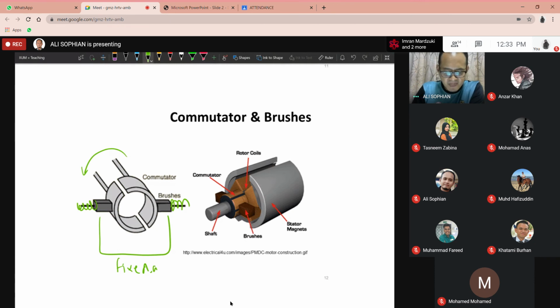The idea is, as the motor or the generator is aging, the brushes get worn out because of the friction. Bit by bit, they will become shorter and shorter, and the springs make sure that the brush always pushes towards the commutator segments, so they always make contact. If there is no spring, the brush will be loose, and it might lose contact, or the contact will be intermittent. Sometimes it's making contact, sometimes it doesn't. This is the function of the spring.